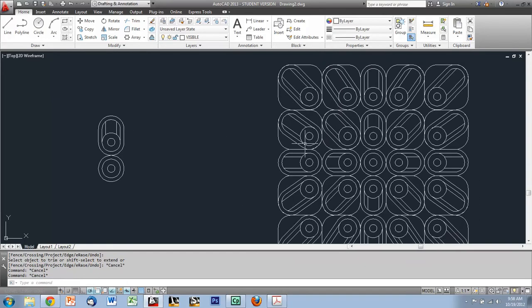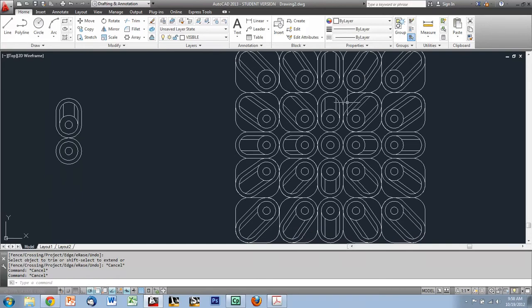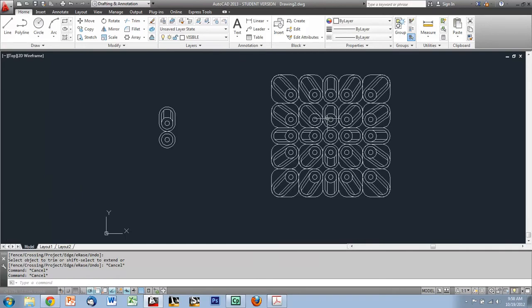And so we've got these first couple of links in here, and at this point you're thinking, wow, this is really going to take forever. I can't believe we have to draw every single one of these links. Well, remember, you've got some other tools available to you in AutoCAD. We don't really have to draw every one of these links. We can use the polar array command after we get a couple of these in here for anything that's repetitive. So the next thing I'm going to do is draw this top link up here, and then we're going to be ready to do a polar array.